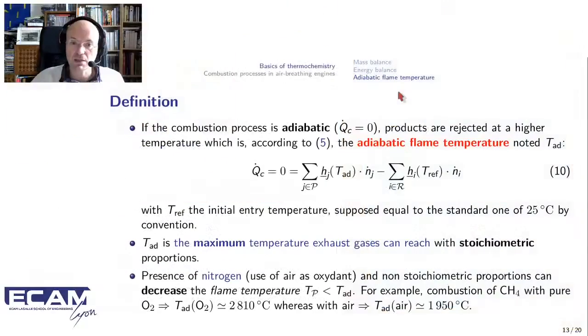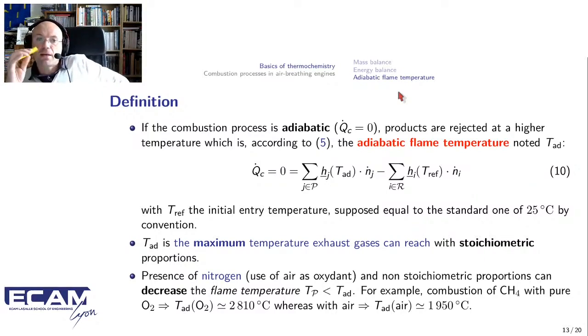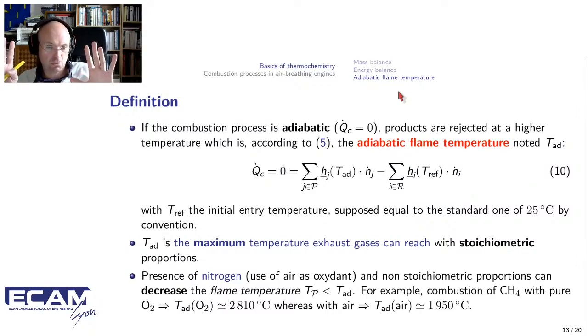Just take a look at this here. You have the order of magnitude of the temperature of the combustion process. So for example, for methane and pure oxygen in stoichiometric combustion, and you just let things go and let temperature rise, you will obtain an outlet temperature which is higher than 2800 degrees. So for a stationary flame, there is no system that resists to this, or it will be probably really too expensive and impossible to use in practical applications. And so we will need to dilute this.